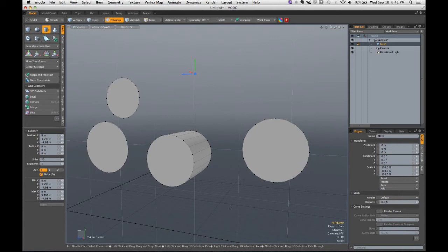Okay, it's down here at the bottom. Doesn't matter where it is, it's got to be very far away from your tool handles. Hold the control key, and then left click and drag. I've noticed that sometimes you get funky results if you left click before you hold down the control key. This is where that disciplined idea really comes into play. Follow the sequence and it will work every single time.